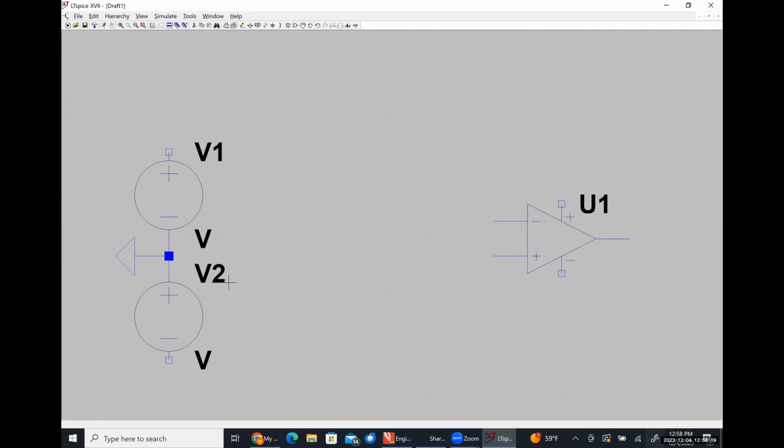So I'm setting up this voltage source for our supply voltages exactly like I set up the supply voltages for op amps physically when we were doing this in circuits 1. I'm putting my two voltage sources in series and then choosing my ground to be that midpoint so that I can get negative voltage and positive voltage at the same time.